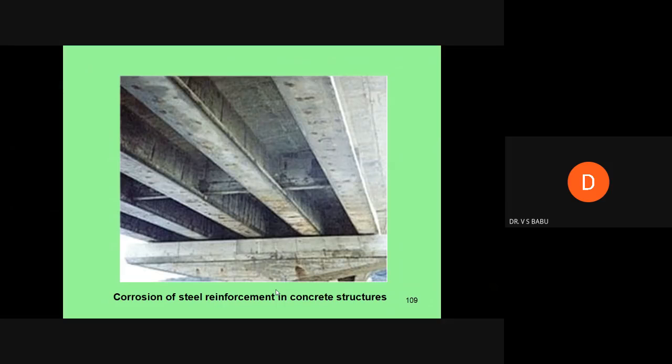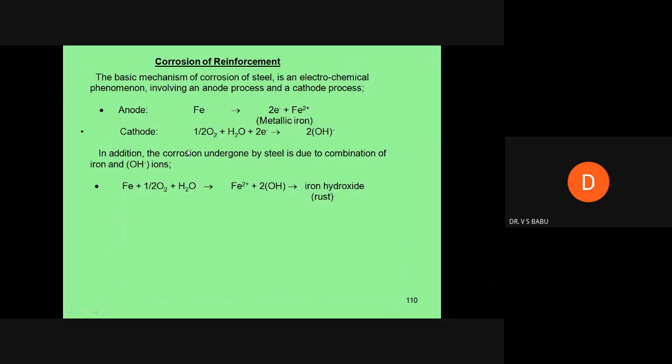क्यों? Because you are taking a preventive coat to the moisture entry. That means moisture entry and oxygen entry के लिए you are prevented with a tight proof coat. That means एक resistive layer provide कर रहा है, समझेंगे ना. Then सरिया को corrosion नहीं लगेगा. Now okay. Now corrosion of the reinforcement. Corrosion very very important. I may ask you one question in the corrosion.